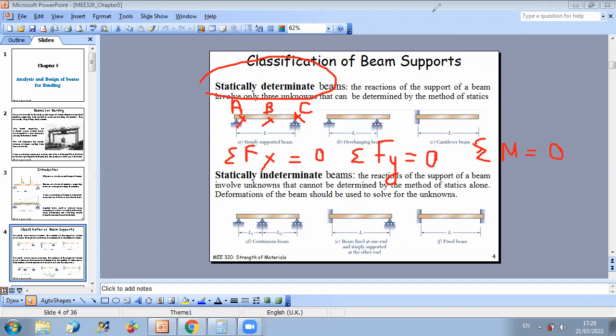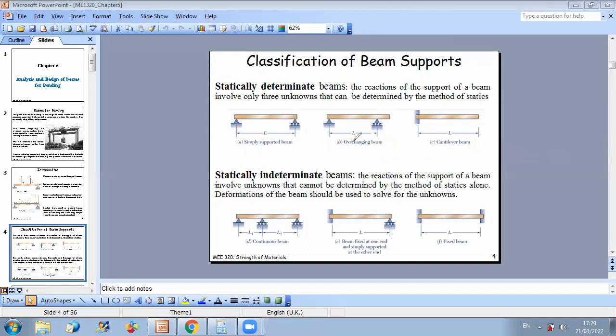What do you mean by redundant supports? So for example, if you have a beam supported by 3 rollers, you cannot consider that this is a statically determinate structure, because using statics, you cannot determine what the reactions are at the 3 rollers. Here, we say it's a case of redundant or improper constraint. It's true that you have 3 unknowns, but they are not properly placed because the 3 rollers can develop exactly parallel forces.